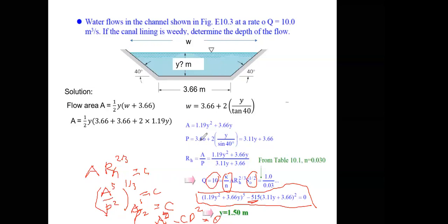So I think that's for today. We have discussed the open channel flow, the characteristic of it, the classification. We can take a look on that flow into 3 classifications based on the uniformity. You have uniform flow or non-uniform flow, based on the Reynolds number whether it's laminar or turbulent flow, and also based on the Froude number, whether it's critical, subcritical, or supercritical flow.